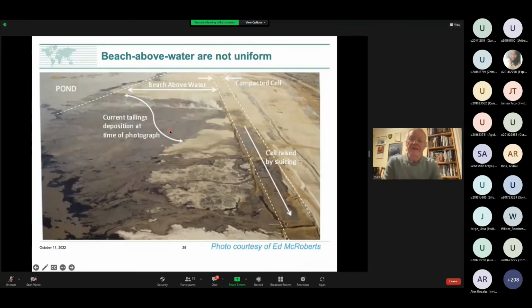I'll give you a photo. This is a photo from the day, back from 1978-ish, not quite 1975. It shows you how they were doing things. They would raise some small dike with a dozer, and then they would discharge the tailings, and they put a weir over here, and the sands would drop out, and the residual tailings would run across there. That was how they developed their cells for arrays over quite a distance.